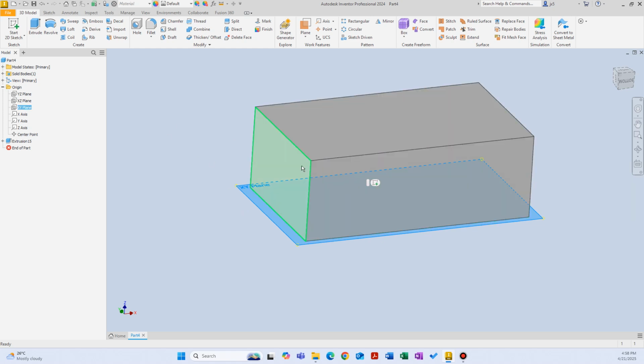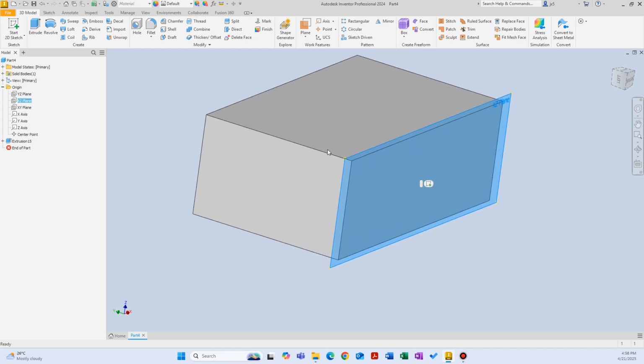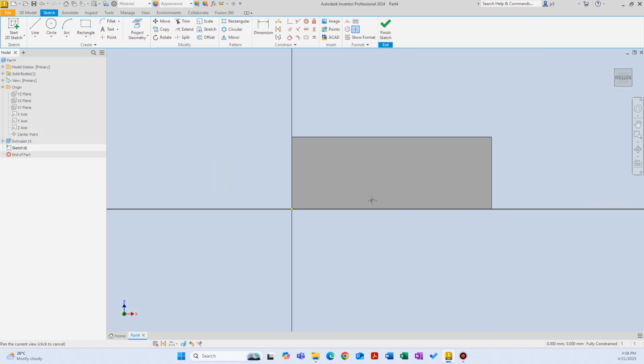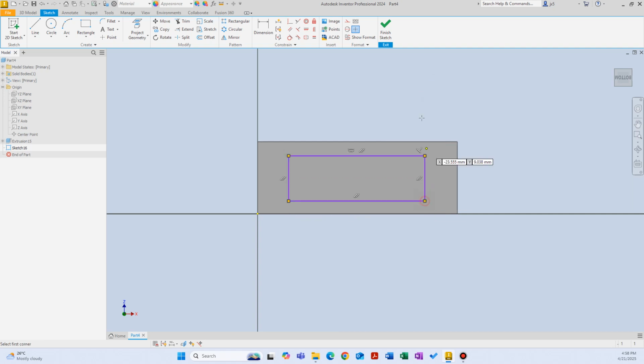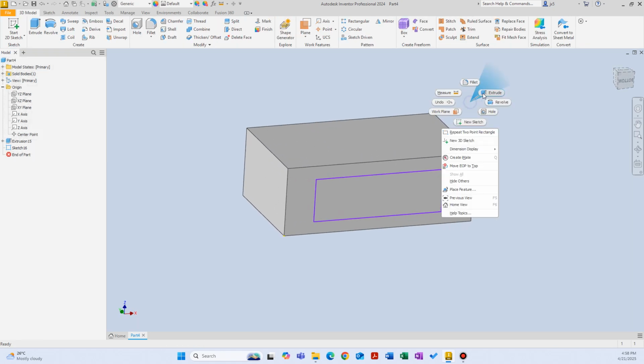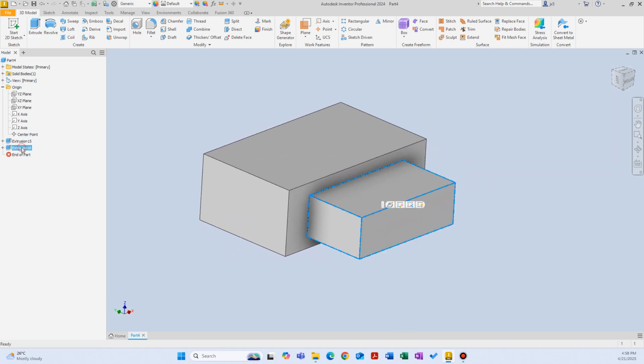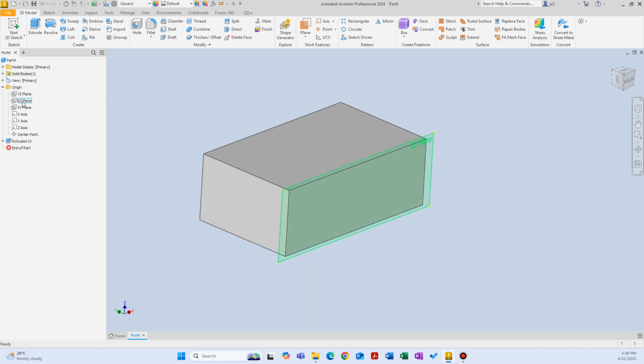And then we can continue to build on this by using this plane, or we can take advantage of the other planes. For example, this XZ plane is on the side of the 3D object, and we can use that to create another sketch. For example, another rectangle here. And now we can finish that 2D sketch and apply another modeling action to it. Something like this maybe. Let's delete the second extrusion and talk about something else. We can use these default planes that Inventor provided us to create sketches on, and then we can apply modeling actions to those sketches. But also, as we create these 3D objects, we also create new surfaces for ourselves.